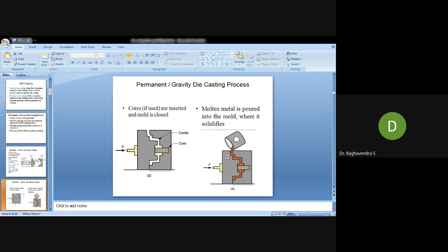So this is a mold, and here itself there's a die. Whatever shape you want, you will get it here. We'll pour the molten metal. Before putting the molten metal, both the molds are preheated to a certain temperature to avoid sticking of molten metal to the surface of this die. So when both are heated, molten metal will not stick to the surface, and whatever profile geometry is created over this die, the same geometry will come out when it is solidified. That's how it works.